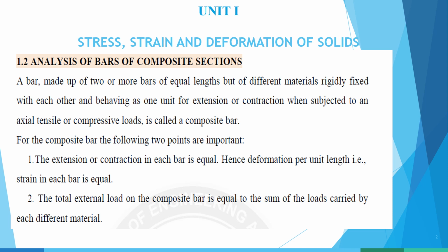The extension or contraction in each bar is equal. Hence, deformation per unit length, that is strain, in each bar is equal. The total external load on the composite bar is equal to the sum of the loads carried by each different material.